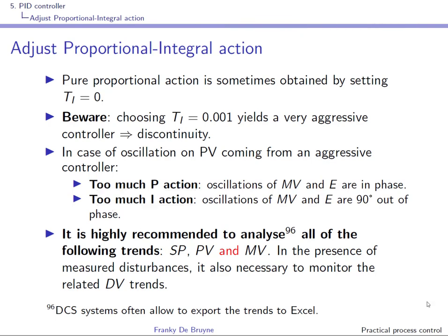When tuning a PI or a PID controller, you should always look at the set point, at the process value, but very important also at the manipulated value. MV is sometimes forgotten, even in reference books. There is much to be learned by observing MV.